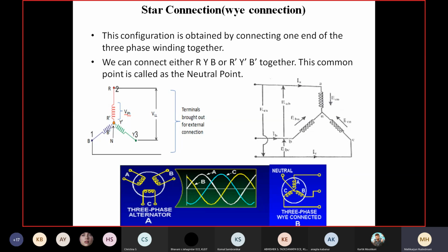Now, what is the line to line voltage? Line to line voltage is the voltage measured between any two terminals or lines. You can see here I wrote EAB. EAB means the voltage between terminals A and B. I have to touch this A which is over here and touch B. Between these two leads, whatever voltage I read is called EAB, because I mentioned A here, B here. Same thing you can see here. Line to line voltage means line 1 open to you for access and line 2 open to you for access. Between these two, if you read the voltage, it is line to line.